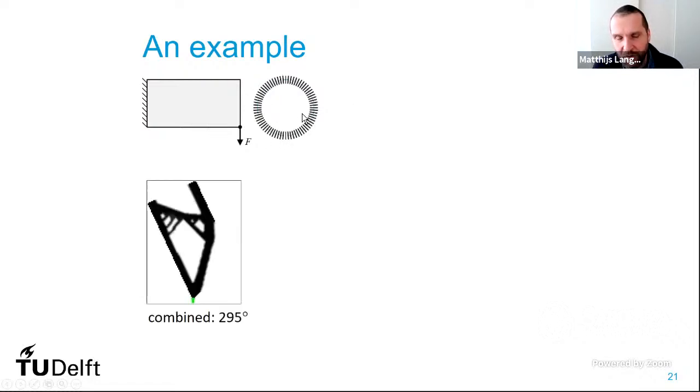That's my discrete orientations, and I optimize them all at once, considering all orientations and emphasizing the one that gives me the best, lowest support. And this is what came out of this process. So at this particular orientation, the performance was best and the amount of support was the least. Whether it's realistic to build a part like this, it doesn't look very stable, so I still need to look into that. But at least in terms of the criteria set, it was the best one.